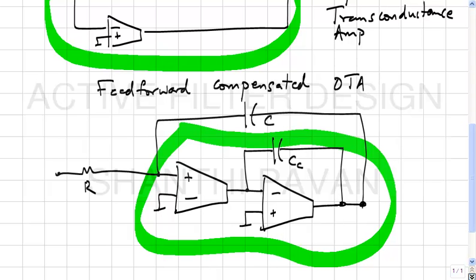Again, as you can see, at low frequency the transconductance is virtually infinite, right, because GM1 flows into an open circuit, generates a large voltage which gets multiplied by GM2 and sucks out a large current. At high frequency, however, what happens? You can think of this as CC shorting the second transconductor, thereby reducing it to a first order system. Does it make sense? And this is nothing but the classical Miller compensated circuit.